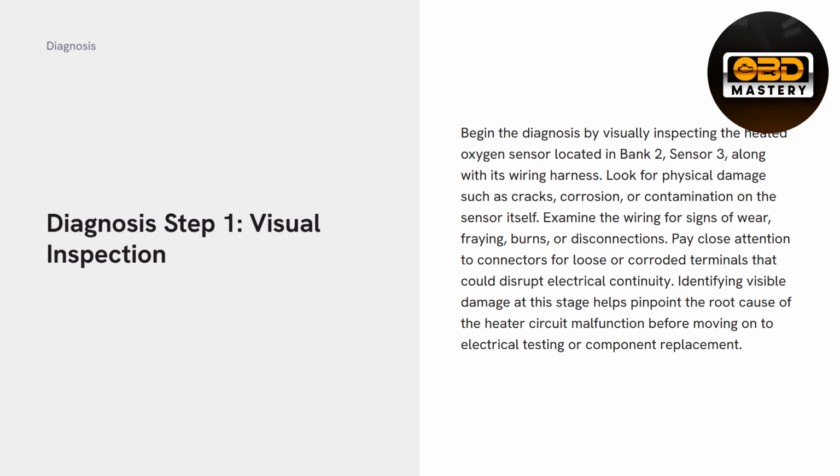Now pay close attention to connectors for loose or corroded terminals that could disrupt electrical continuity. Identifying visible damage at this stage helps pinpoint the root cause of the heater circuit malfunction before moving on to electrical testing or component replacement.